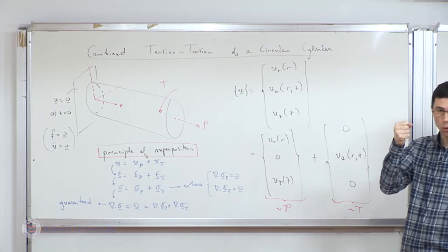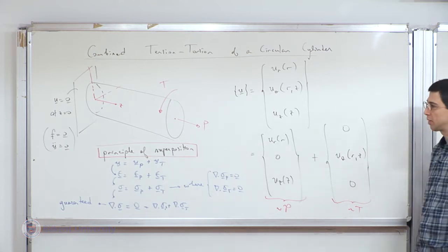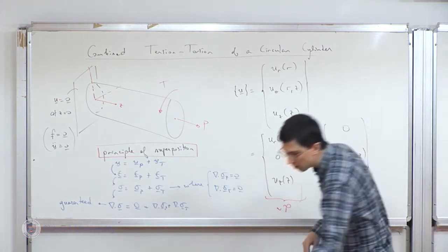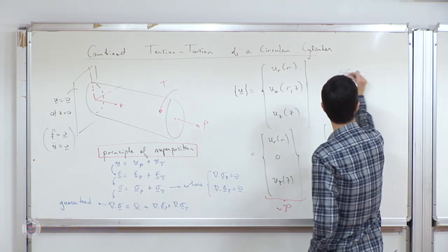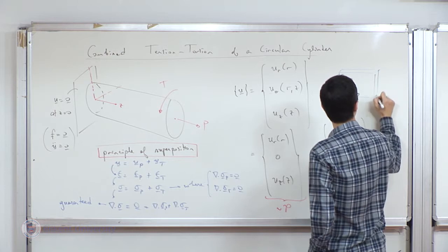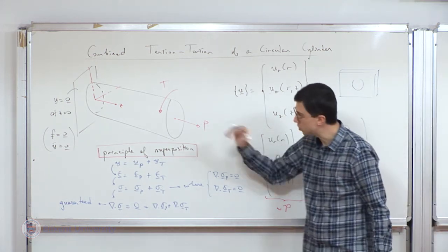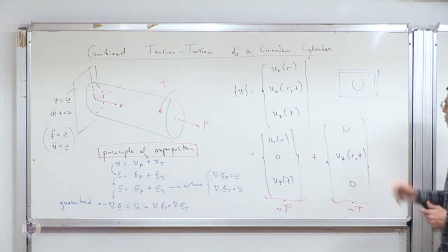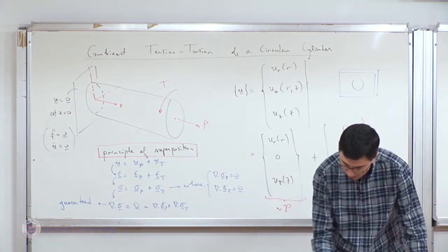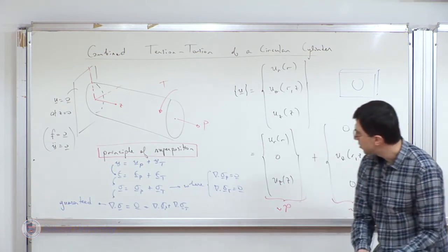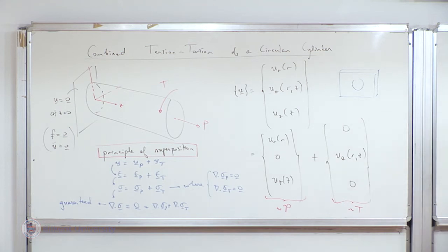It's a plate with a hole. You'll pull on it, and there's a stress concentration effect eventually that you can observe. But the solution of that problem is not a particularly simple one. Okay, so it's a problem that looks like this. Right? Plate with a hole. We're going to pull on it. There is no obvious symmetry to the problem, but under certain assumptions and by also making use of the principle of superposition, you will be able to solve such a seemingly quite hard problem, but in the homework, not in lecture. Okay, so with that, I'd like to conclude the displacement-based solution.